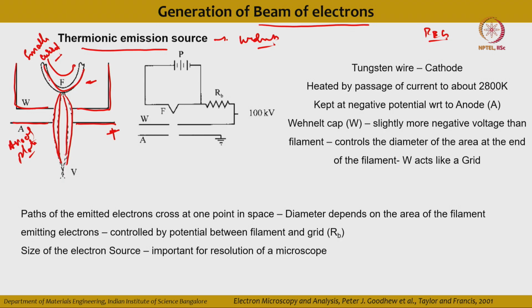So, there is a tungsten filament which has a certain radius of curvature, and you are applying a very high potential at the anode so that it will extract the electrons from the tungsten filament. Now, if you are not applying any voltage, there will still be a small current passed through the filament, and that particular current is called a dark current, okay. So, even though the electrons are not extracted from the filament, there is a current passing through it, which is called a dark current. It means that it flows before it emits light, or it emits electrons.